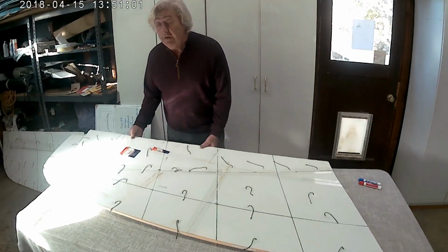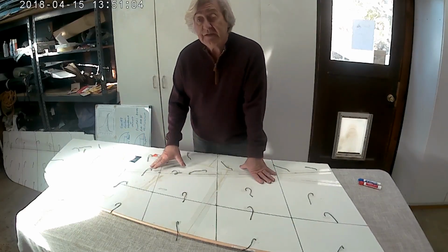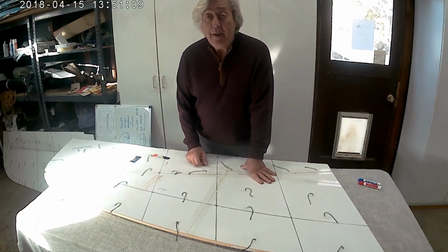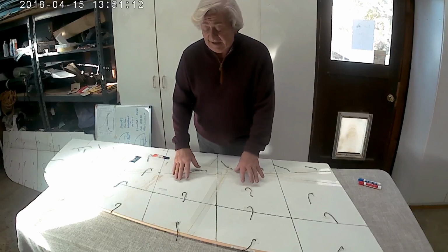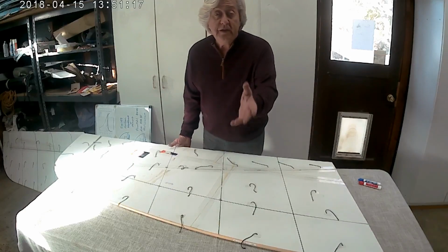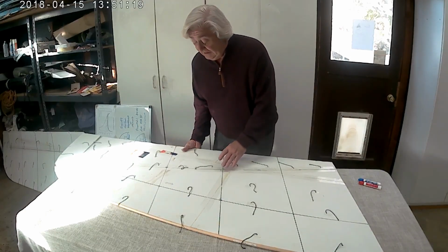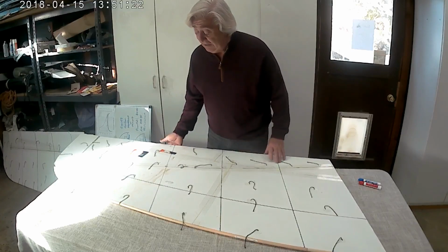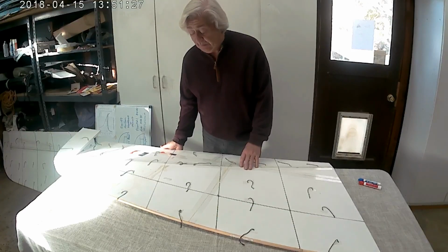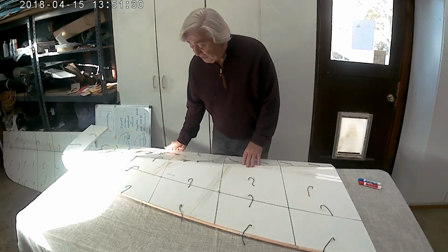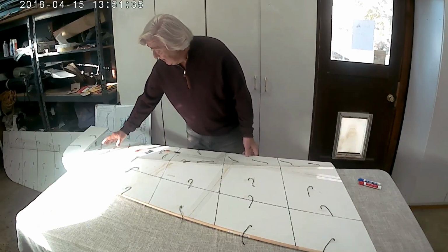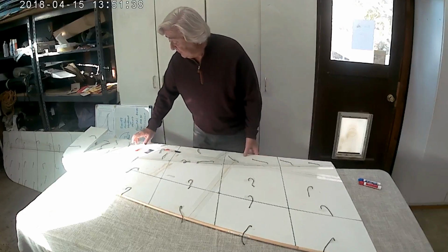And if you've been watching my videos, you know I went through a series of design changes on my wing. Lumps, sealing the gap, making the elevon taller than the main wing panel, all kinds of stuff to try to energize the flow. Oh yeah, even trip strips and turbulators, vortex generators. Man, I've tried everything. And I would get small increases, 10, 15% more deflection available to me before it separated, but not like this. I got a good chunk of the elevon where the flow is straight before it goes off the end.